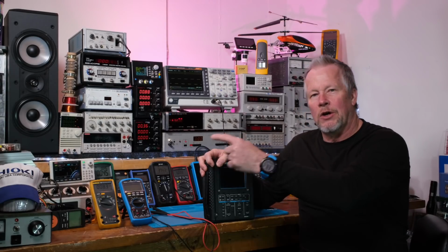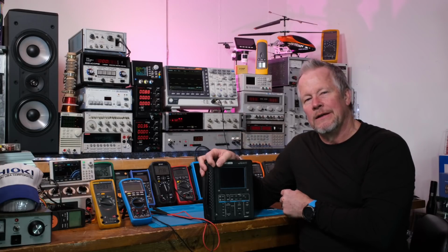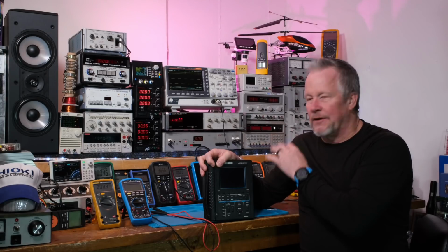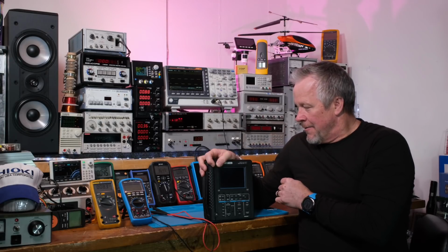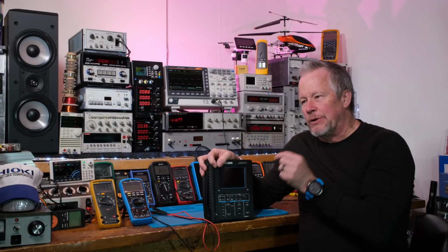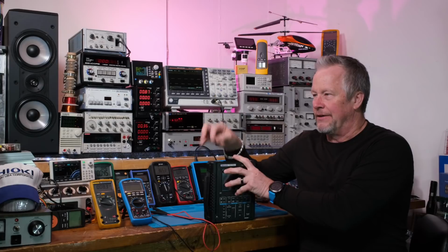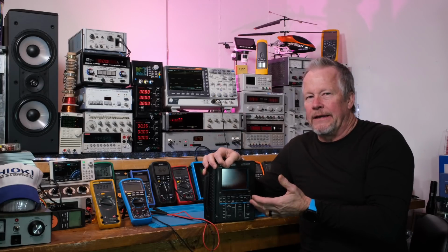So there's no current that's shared between the primary power coming in from the wall and the stuff you're powering, the circuits. Galvanic isolation is when you take an ohm meter and you put it, say, from primary ground to secondary ground, you don't read any current flow. There's lots of ohms, okay? Mega ohms, whatever. I mean, it's open circuit. So that's galvanic isolation, where there's no DC current path.